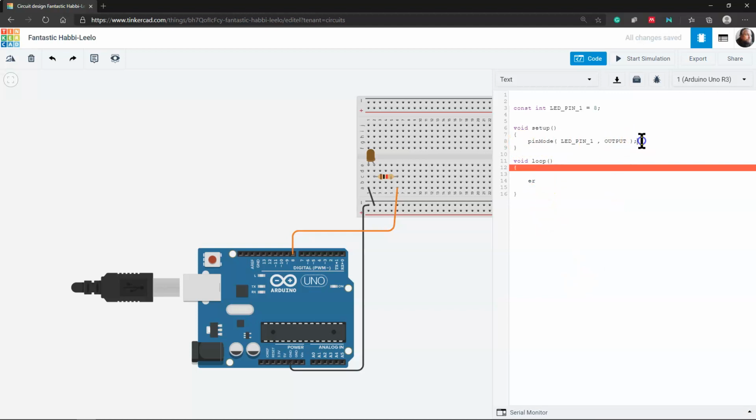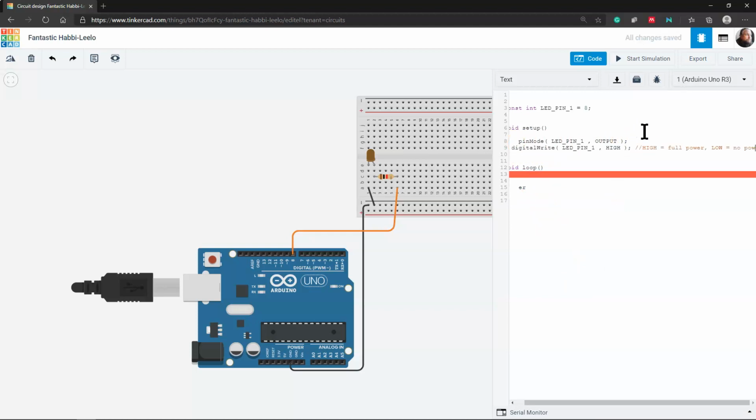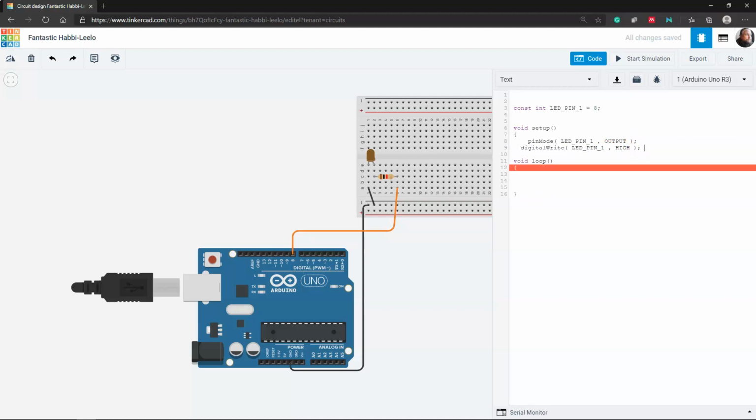So it's going to remove that out. I'm going to put it up here in the actual setup. Remove this, remove the comment for now. I'm going to do it in the setup, which is purely legal. Make sure I got that closing curly bracket. So what this means in the setup is that it's going to call it once. The setup is going to exit. We're going to loop. There's nothing in here, but up here, we've already told the pin to be on high. So after this point in time, until we do another call to low, it'll just stay on.